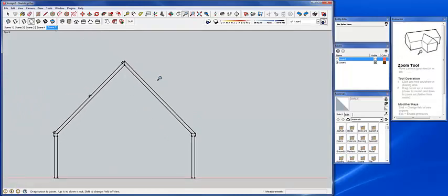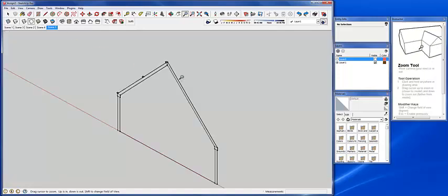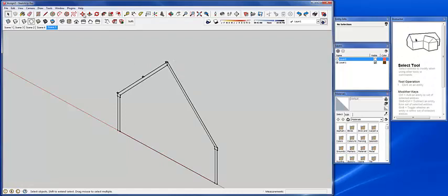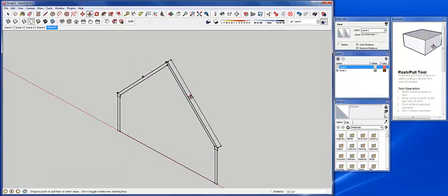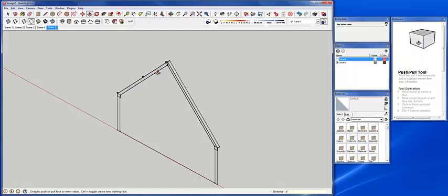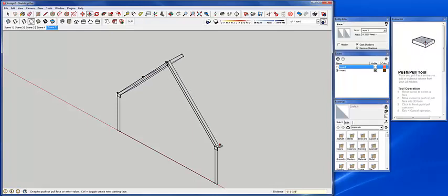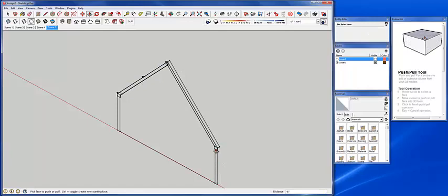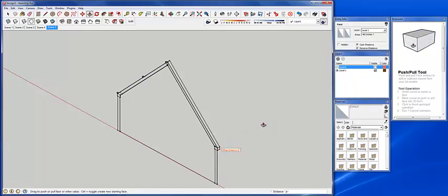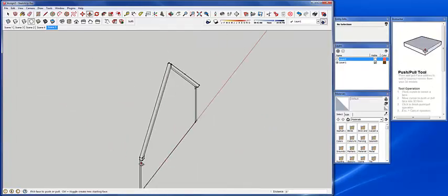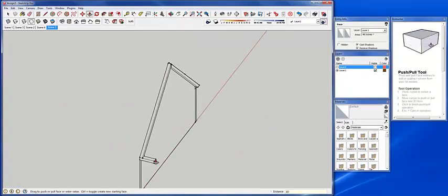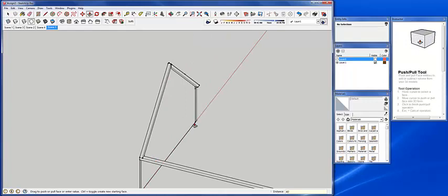But here, that's actually enough for us to get into sort of the construction. You guys can repeat that. So again, I'm going to go into sort of isometric view, and then using the push and pull command, I'm going to start to give this depth. So we can start to push that, and we'll say that that's 6. And then we can use our reference edges once we have them. Pull that out. We know that that's 40 feet.